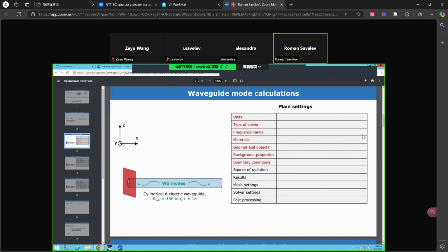The first option: you build this model, a cylinder bound by a calculation domain without a port first, and then you create the port which fills the whole YZ plane. Then the size of this waveguide port would be defined by the background distance that you chose. Another option is you set the size of this waveguide port by yourself.